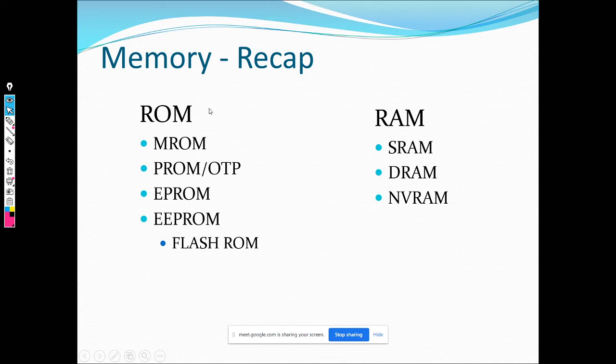If you see, this can also be seen as the technological advancements of the ROMs. To start with, there is something called MROM. MROM is masked ROM. These are one time programmable ROMs. When they are fabricating, the memory is etched. It's done at the fabrication level. Once the fab is done, you're masking it, and it's hardware. It's designed to read those bits. So you cannot alter them by any means at all. Those are the masked ROMs.